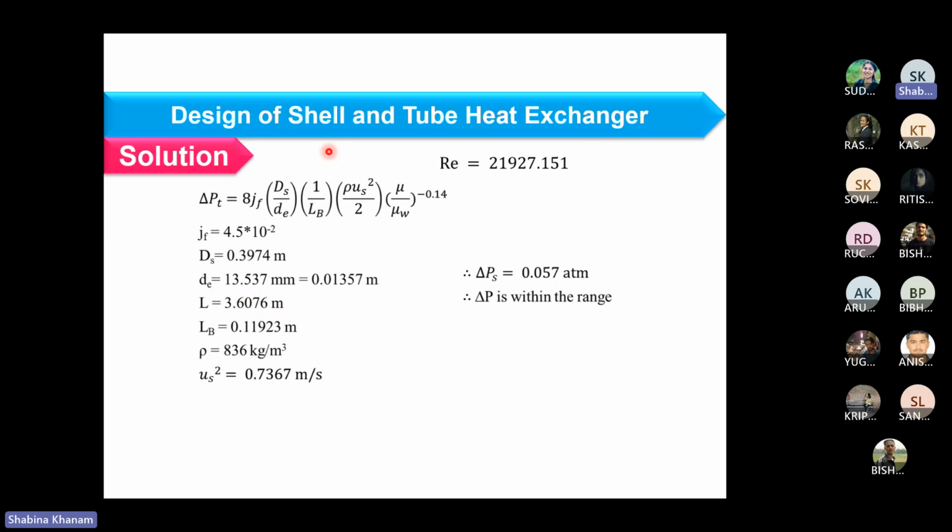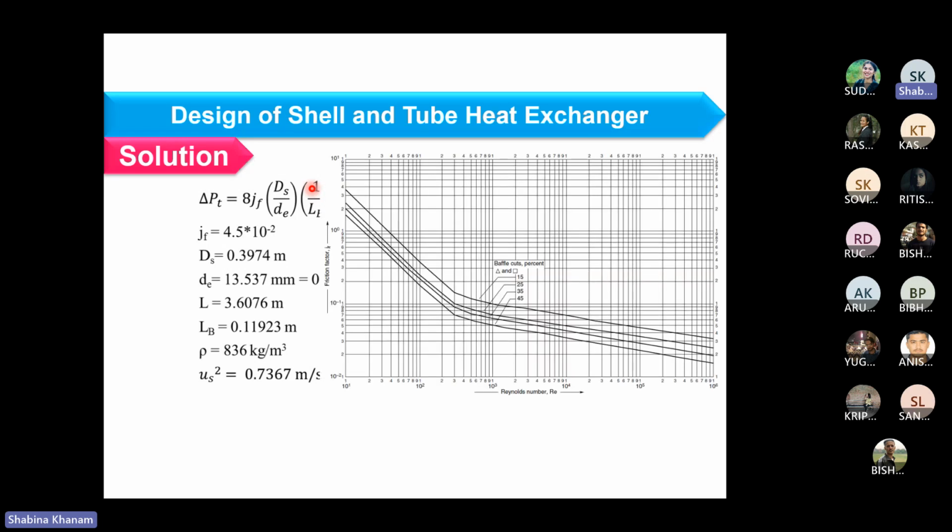So please keep in mind when you are calculating pressure drop on the shell side, this capital L should be L effective, not the total length.